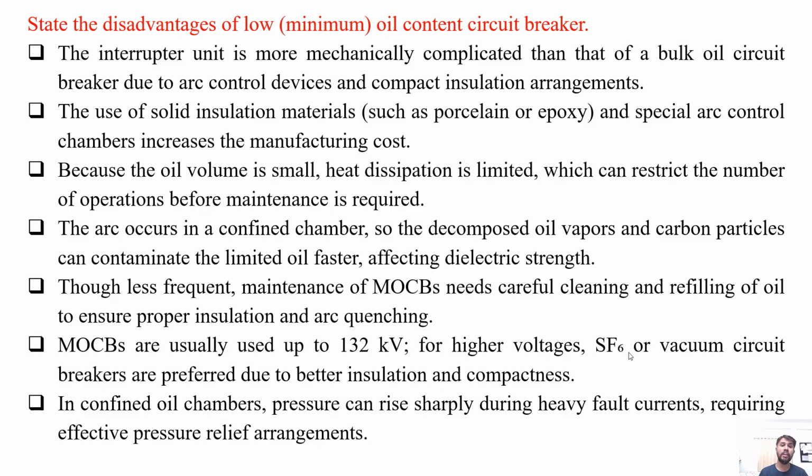Now, because the oil volume is very small, heat dissipation is limited, which can restrict the number of operations. Arc occurs in a confined chamber, so the decomposed oil vapors and carbon particles can contaminate the limited oil faster, affecting the dielectric strength of the breaker. Though less frequent, maintenance of minimum oil circuit breakers needs careful cleaning and refilling of the oil to ensure proper insulation and arc quenching in the breaker.